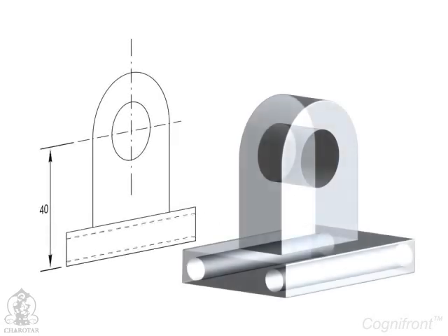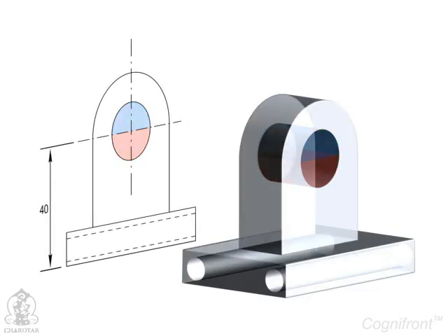Hidden lines are shown with medium thick lines consisting of short dashes and are used to represent invisible edges and surface boundaries. Center lines are thin lines drawn with alternate long dashes and dots and are used for representing symmetrical objects. Then there are dimension lines, extension lines and cutting plane lines.